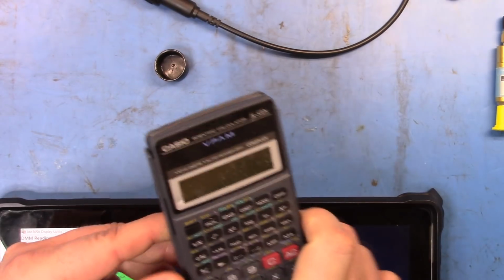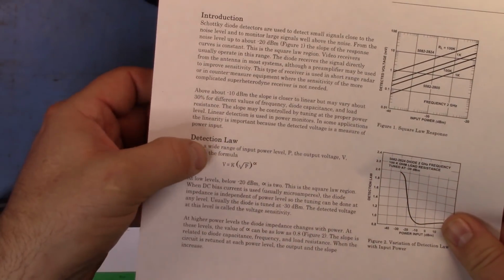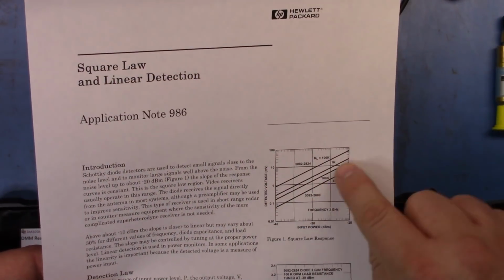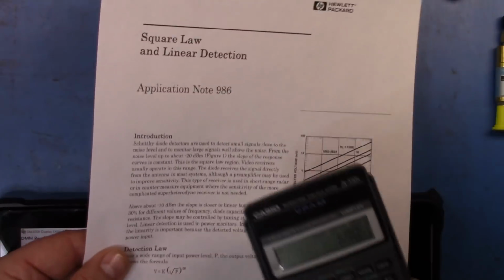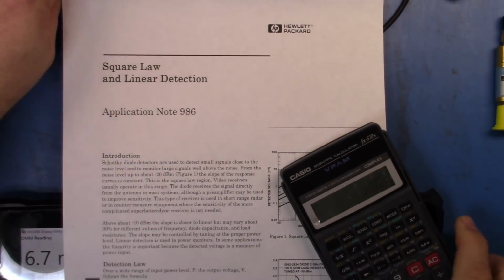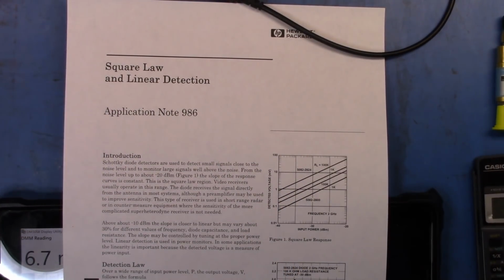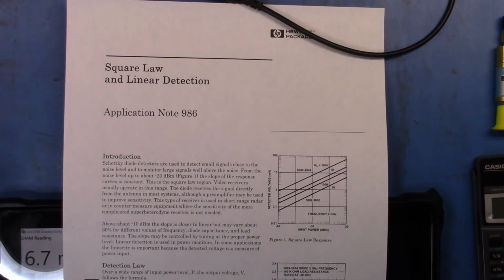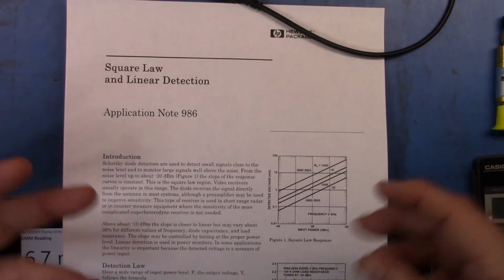So to work out K from this formula, using the crystal detectors in that sensitivity region, was fairly straightforward. And for this particular sensor that I have here, it's about 670. Now, these are not metrology grade connectors. There's some loss in the cables, all that sort of thing. But that takes you through the process of how to get that.